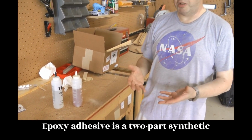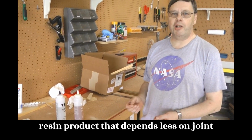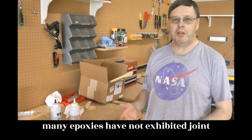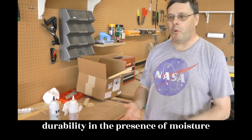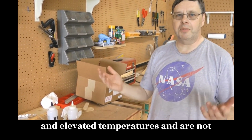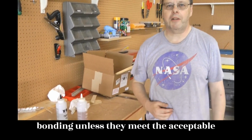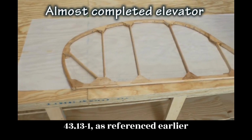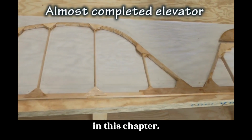Epoxy adhesive is a two-part synthetic resin product that depends less on joint quality and clamping pressure. However, many epoxies have not exhibited joint durability in the presence of moisture and elevated temperatures and are not recommended for structural aircraft bonding unless they meet the acceptable standards set forth by the FAA and AC 43.13-1, as referenced earlier in this chapter.